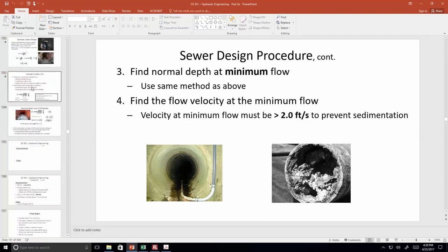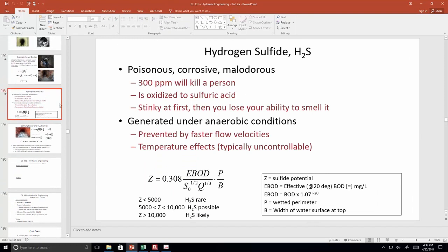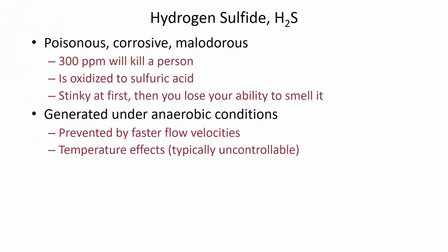All right. One last thing we're going to talk about today is hydrogen sulfide. It's a dangerous gas that can actually cause people to die. And it does. Every year, people die of hydrogen sulfide. And if you've ever driven by people doing sewer maintenance, look carefully next time you do. If they're doing things right, they're really cautious. The guy who's going down will have a tether on him. They'll have a hydrogen sulfide detector. There's someone at the surface ready to pull the guy out if he becomes unresponsive because of this gas.